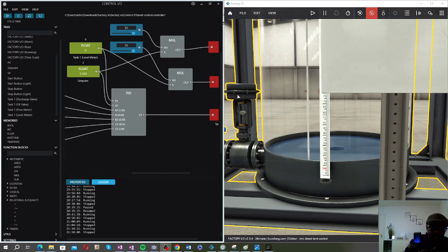Yeah. So this is the pneumatic valve we saw just now. This is the outlet valve, and you use air. When the air comes from under, it pulls this rod up. It's called the actuator. It pulls it up, and it opens. Probably it could be a gate valve or something. It opens it and allows liquid to flow out. And if it's an air-to-close valve, the air comes from on top. There's a diaphragm here, and it pushes on the diaphragm, and it closes. So it could have an air-to-open or air-to-close valve, depending on the configuration, and they all have their advantages and disadvantages.